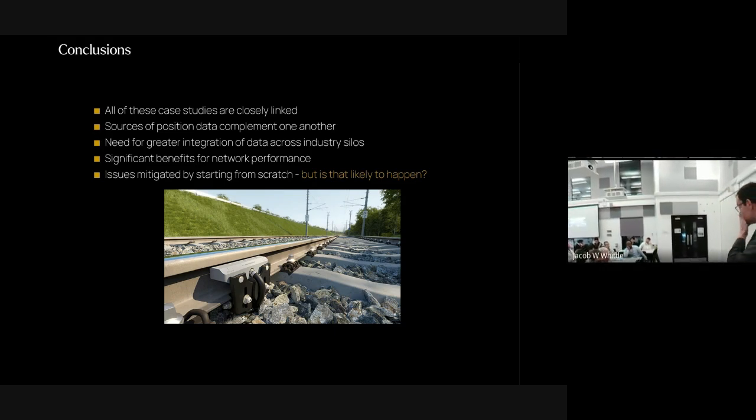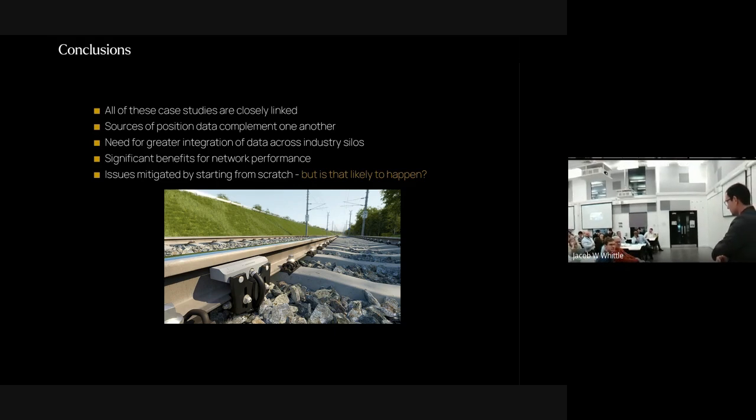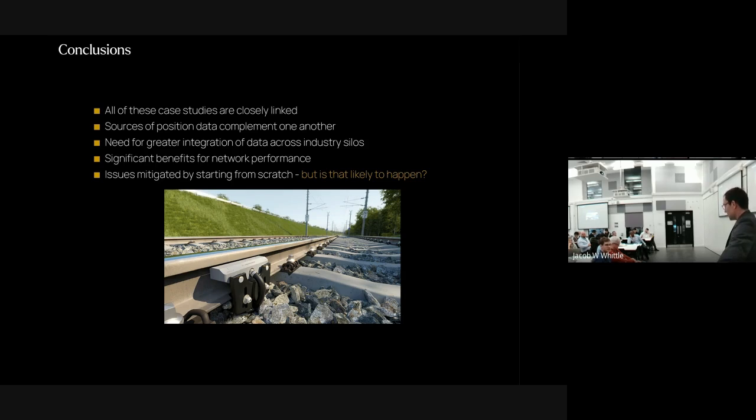So I'm doing my research in ETCS level 2. I wanted to ask you, because we already have a pre-existing infrastructure in place, obviously, we need to retrofit the ETCS level 2 to our existing lines. That's the plan of Network Rail from what I've heard, rather than roll out level 2, or do level 3, as you said, but that's out of the picture for now. And the question is, have you considered how we're going to combine the data? Because how are you going to use balises, for example, to further improve the estimation of where the train currently is, and has this been considered, like how it's going to work with pre-existing infrastructure?